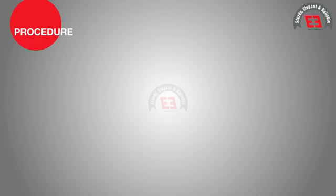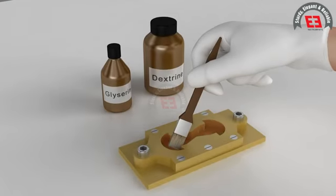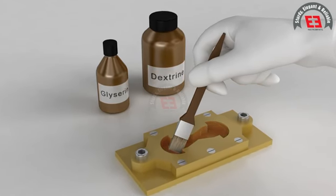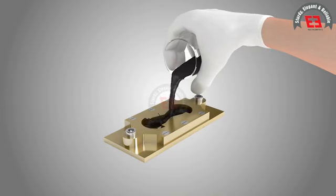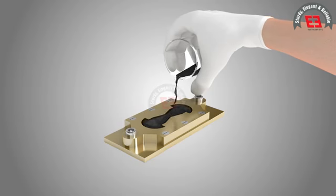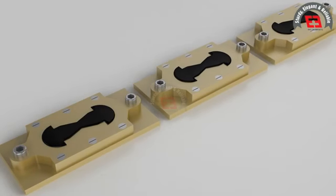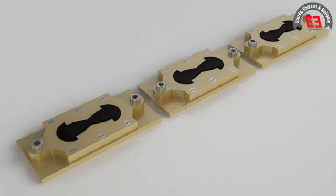Procedure. The bitumen sample is heated to a temperature of 75 to 100 degrees Celsius above the approximate softening point until it is fluid. The solution of glycerine and dextrine is applied on all surfaces of the ductility mold where bitumen is exposed. Now, bitumen is poured into the ductility mold assembly until it is more than level full. A total of 3 specimens of this type are prepared to conduct the test simultaneously.